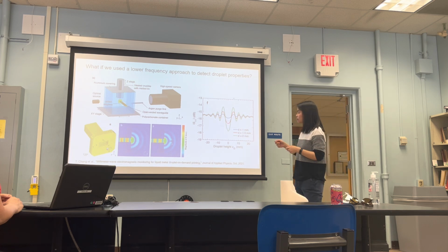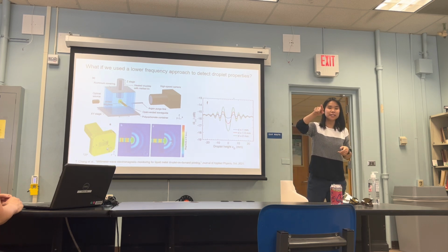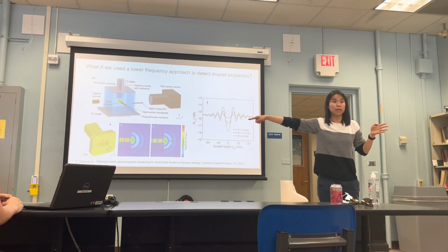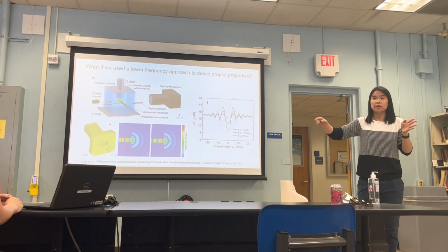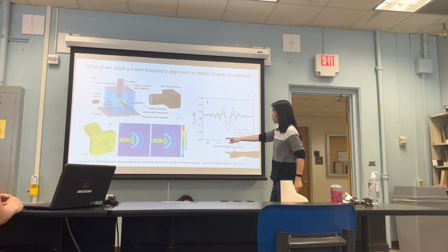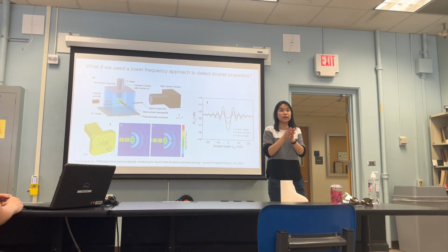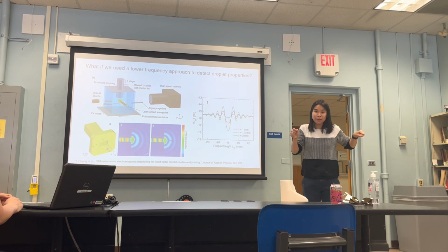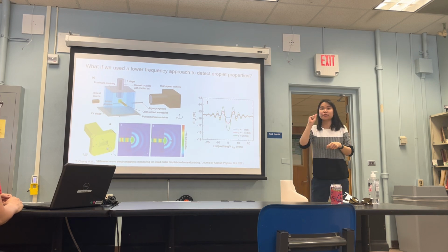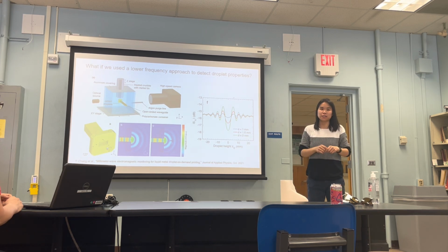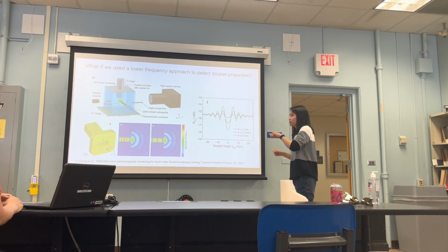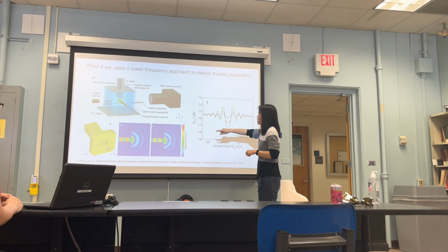So the horn antennas are optimized for far field propagation, right? They're very efficient. But in this case, what I wanted was actually just high sensitivity right next to the aperture of a waveguide, right? Put something as close as possible, because these droplets are 1 millimeter or smaller. And so I wanted as good sensitivity as I could have. And so I just put this waveguide right next to the droplets coming down.